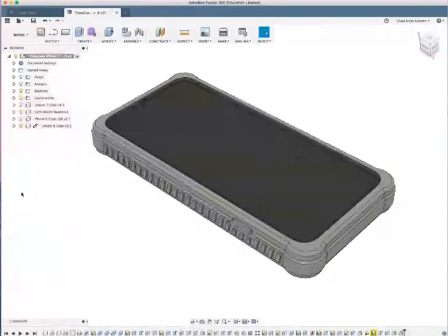Okay, so what does parametric and direct modeling actually mean? If you want to break it down, for those who are not 100% familiar with it, parametric modeling means I can capture every design step that I do. It's like step 1, 2, 3, 4, 5, 6, 7, and then you can always go back in time and manipulate each command. In Fusion 360, for example, it is a horizontal arrangement. In SolidWorks or Inventor, it's a vertical arrangement.